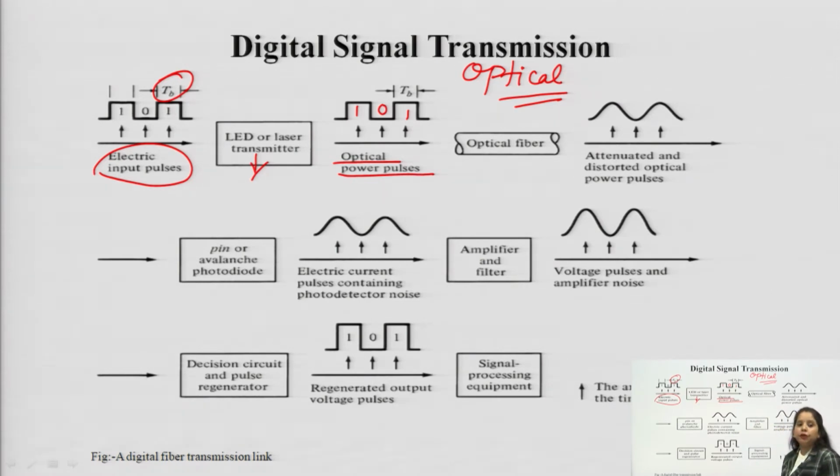Now, when it is converted into the optical signal, it gets transmitted into the optical fiber. Already known to you, when it passes through the optical fiber, it gets attenuated at the various sections. During the attenuation process, our pulse gets distorted, of course, it gets broadened. Various types of attenuation and broadening processes we have already discussed when discussing attenuation, which is a part of unit 2 of your syllabus. So, the signal gets distorted and broadened in this form, but again it is the 1 0 1 signal, attenuated, because you are seeing that the shape changes.